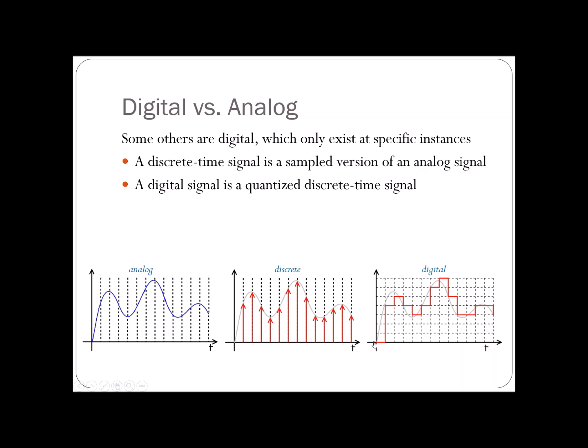But of course, if you look at this digital signal, the points might not really coincide with the real analog data here. Why? Because the value that you record is also discretized. So you only record the point which is closest to this real analog signal.